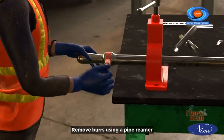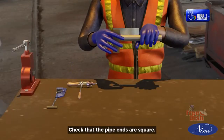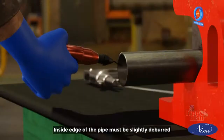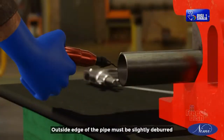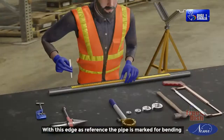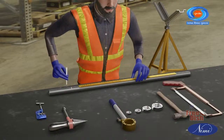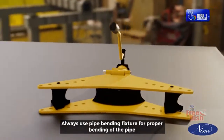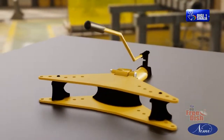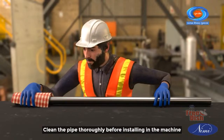Remove burrs using a pipe reamer. Check that the pipe ends are square. The inside edge of the pipe must be slightly deburred. The outside edge of the pipe must be slightly deburred. With this edge as reference, the pipe is marked for bending. Always use a pipe bending fixture for proper bending of the pipe. Clean the pipe thoroughly before installing in the machine.